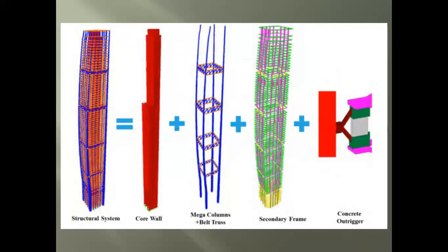And it is surrounded by materials with less weight, like you see in this picture, with mega columns and belt trusses. So here we see our outrigger systems. Not on each level, but at special heights. I told you the tall buildings can be divided into 3 or 4 parts, and each part is a separately increased bearing system, which includes the outrigger system.